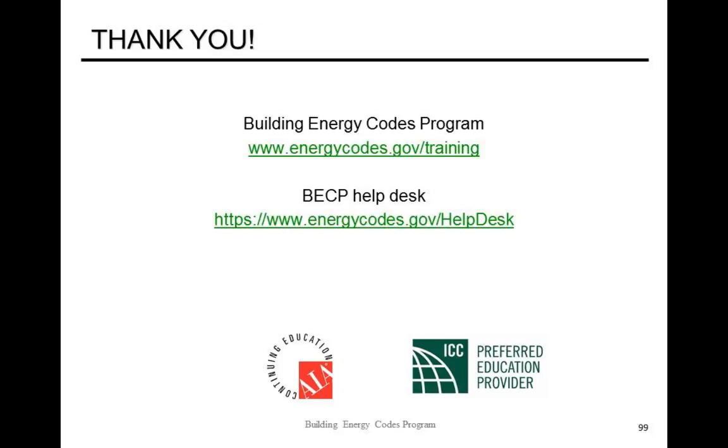We feel, and I think DOE feels the same, it's a better metric to really measure the efficiency of a rooftop, because they seldom, if ever, run at full load, which is where our primary metric is. A lot of the HRI sections are now starting to evolve to metrics like this, whether we call it IER or IPLV. That's where we're going. We are planning some further improvements to look at more ventilation load, and whether we can include economizers and heating. Those will be future things we're looking at. So I'll stop there with those three questions.